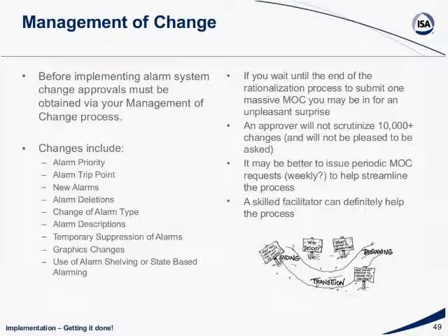Okay, talk about management of change. And really, you can't do the implementation until you've gotten approval to do the implementation, and you get your approval for the whole management of change process. Waiting until you've rationalized 10,000, 20,000 different changes is probably not the best idea. What I've done with clients, I've got a specific format I use for alarm management when it comes to developing the MOC document. And at the end of the week, I issue that MOC document to my client, and then they can take that on for interim approval. And one of the real benefits of this is that, number one, it becomes much more manageable.